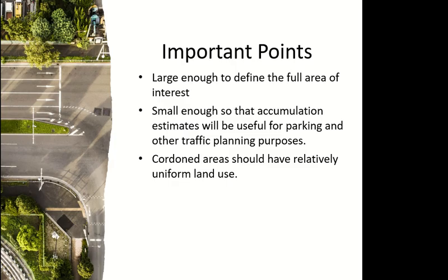Now, what about the minimum size? Sometimes in an area, one particular facility can be dominant. For example, let's say you go to Seef area. In Seef area, the biggest attraction could be City Center. Now, somebody may say, since most of the traffic is coming because of City Center, let me make my boundary around City Center only. Now this is too small. You are missing the other facilities that can combinedly generate a lot of traffic.